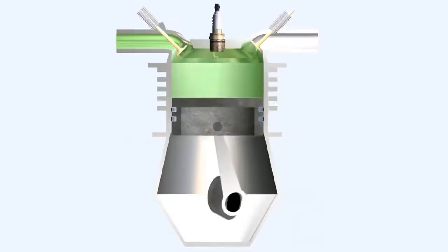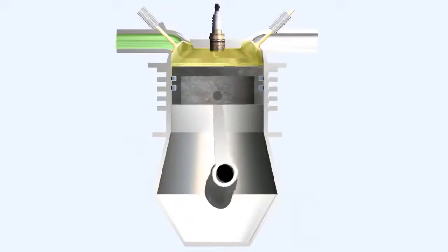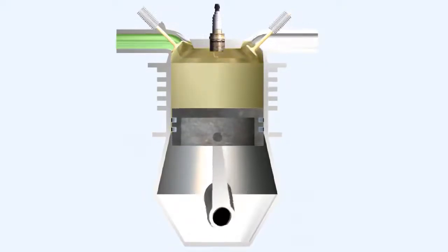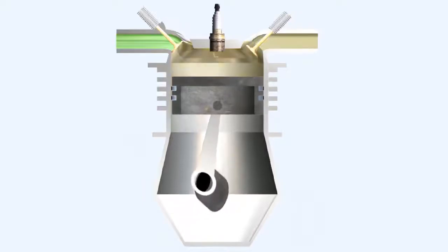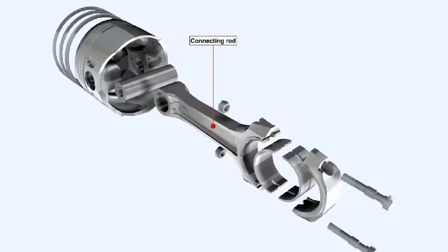The connecting rods transmit the forces of combustion to the crankshaft, and assist in the conversion of the linear motion of the pistons into the rotary motion of the crankshaft. A connecting rod is usually made of H-section high-tensile steel, which combines lightness with the strength necessary to withstand both the compressive and the tensile loads which are imposed, as the piston changes direction at the end of each stroke.